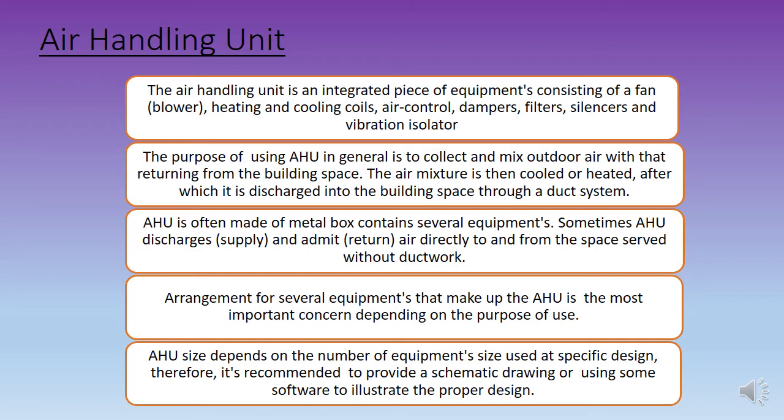Alright, so let's talk about the air handler unit, or air handling unit. It is actually an integrated piece. It consists of a blower or fan. We have heating and cooling coils, controls, dampers, filters, and silencers, to insulate the noise that is caused by the air velocity, and also a vibration isolator.